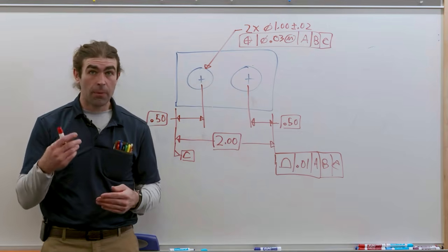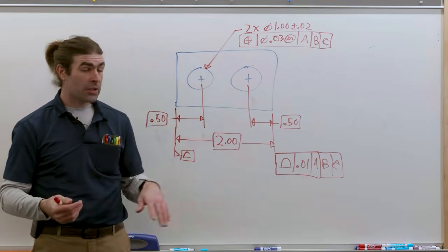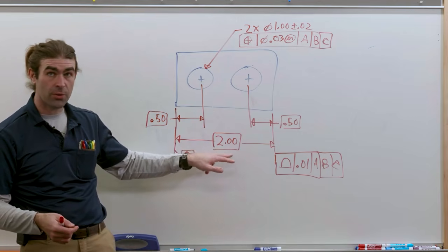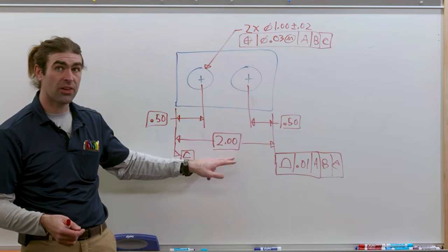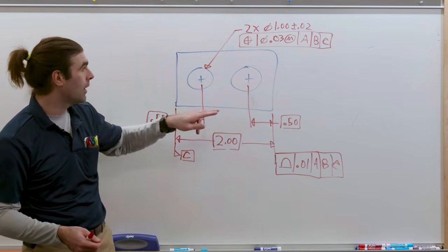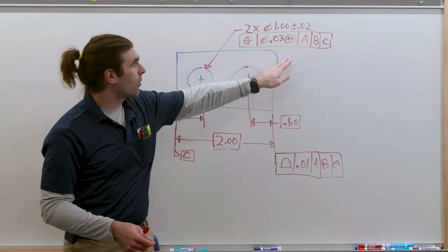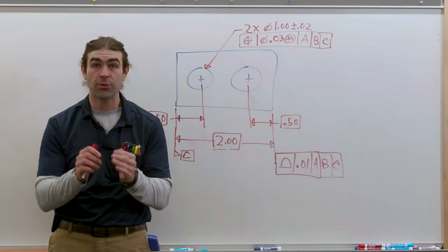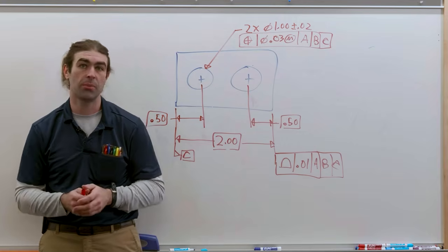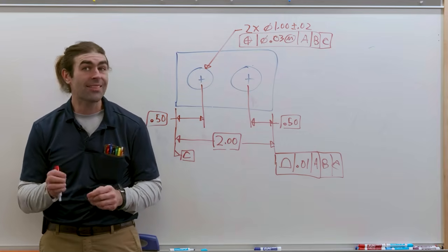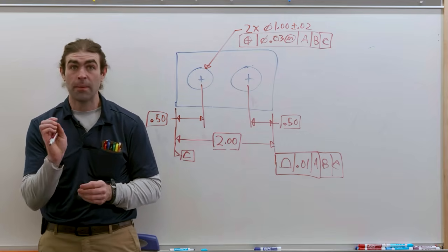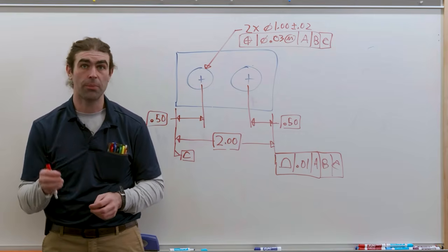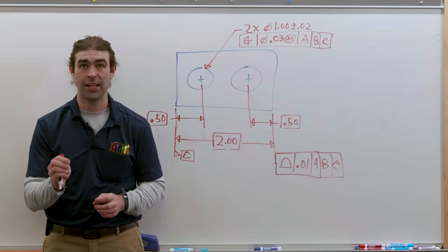Now, at inspection, you really shouldn't indicate the tolerance or the actual dimension for basic dimensions. All of these dimensions here are associated with either this position or this profile. That's where the tolerance for the basic dimensions is. And the last thing about basic dimensions is that they must come from datums. That's where you're measuring from. The basic dimensions have to lead back to datums.